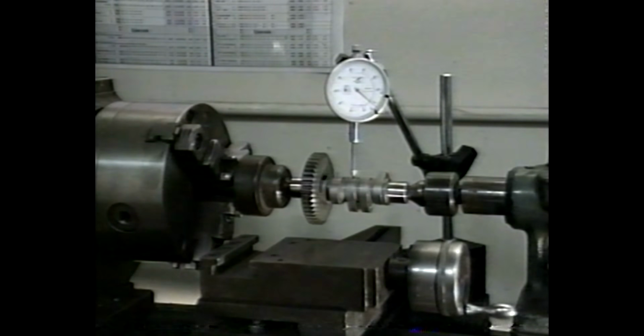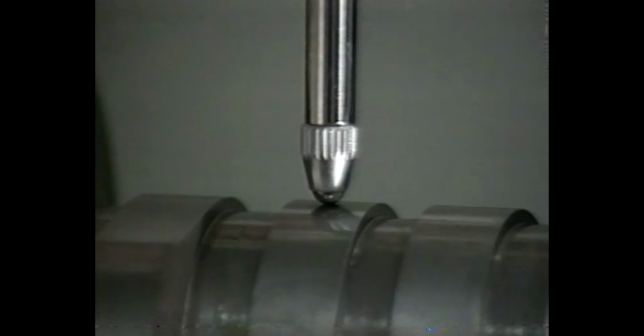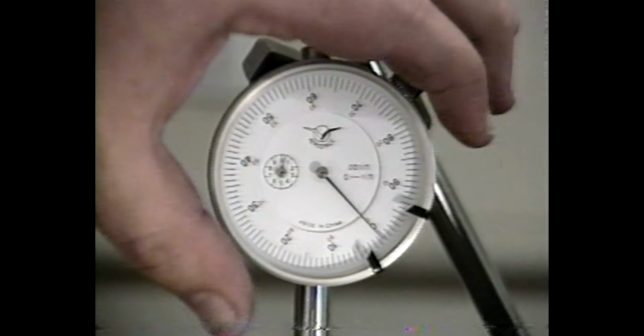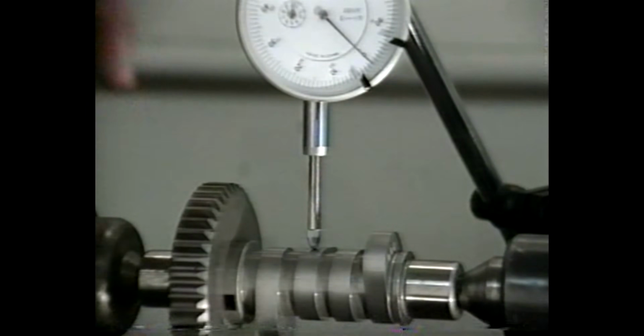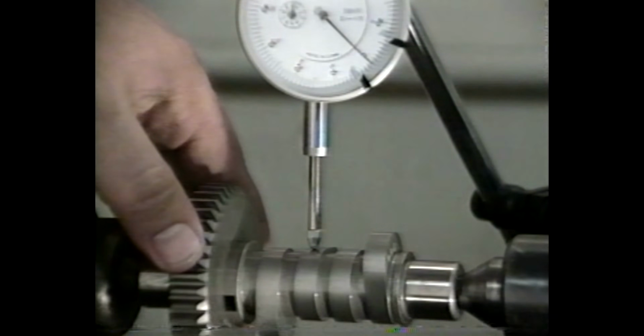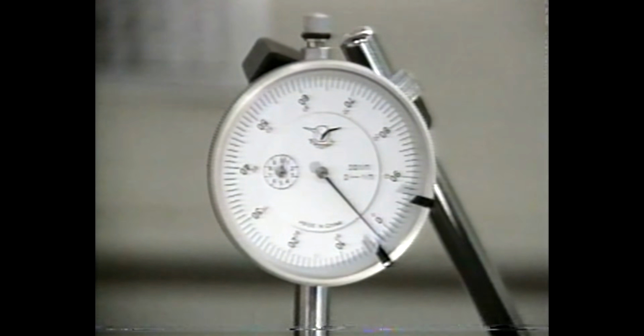To measure the net cam lift, we place our camshaft firmly between the centers in our lathe. This time, we place the dial indicator directly onto our camshaft. Once again, we zero our dial indicator to the base circle diameter, as we did previously. Then, we slowly rotate our camshaft until the needle starts to move off zero, where the ramp of our camshaft begins. We mark this point.